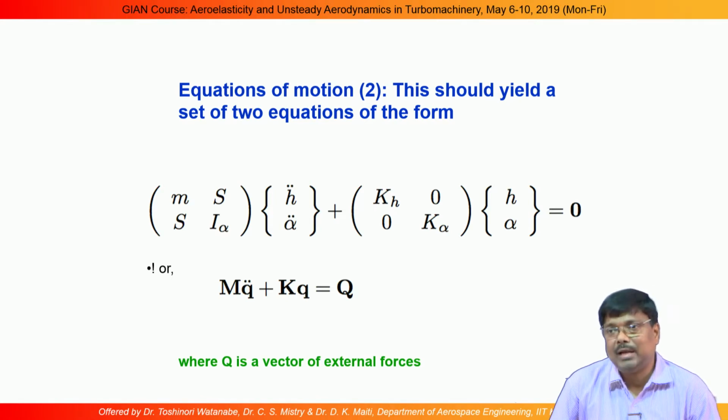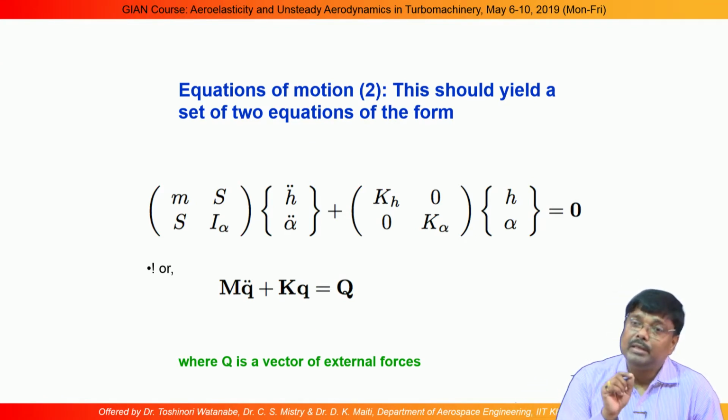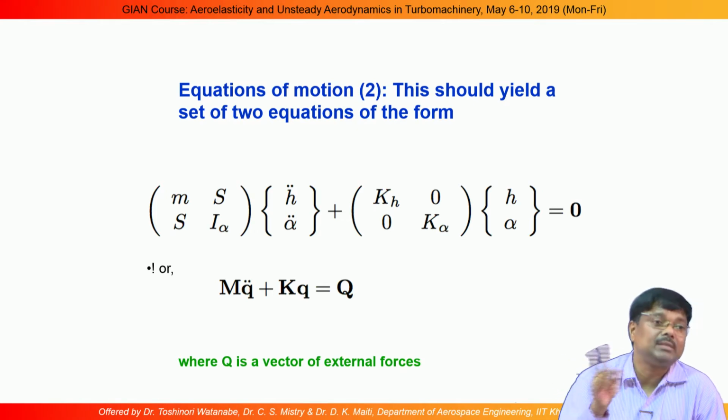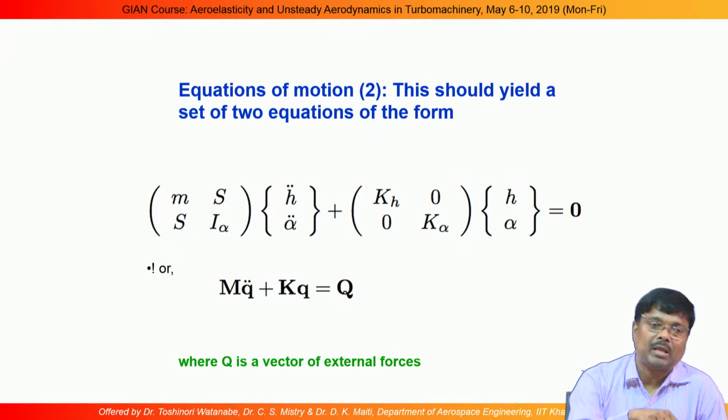If you look at that, let us say the x axis is the stiffness force, then the damping force will be acting perpendicular to that, because between displacement and velocity there is a 90-degree phase difference, and between displacement and acceleration there is a 180-degree phase difference.